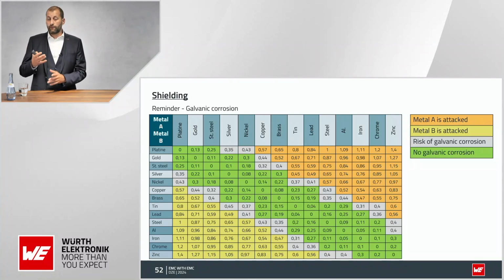Why? Because some materials are going to be attacked, and so in this case, I don't know, an anode or a cathode is going to be destroyed, and therefore your battery is going to die. This effect can be speeded up by quite a lot if we introduce salt water or any acid liquid. What do I mean by that? We did tests in-house where we made a gold connector and a tin plated connector, and after I think 128 hours of salt spray test, tin was completely vanished.